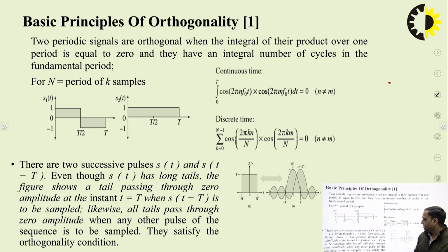Okay, right. So this is the principle of orthogonality. One of the major effects of multi-carrier modulation is that we have to use different frequencies which follow orthogonality. Orthogonality means the null points cross over each other; the null point of every frequency spectrum must coincide with the others. In that case overlapping can be avoided, and when there is no overlapping, ISI can be reduced. We will discuss some properties when we talk about the principle of orthogonality.